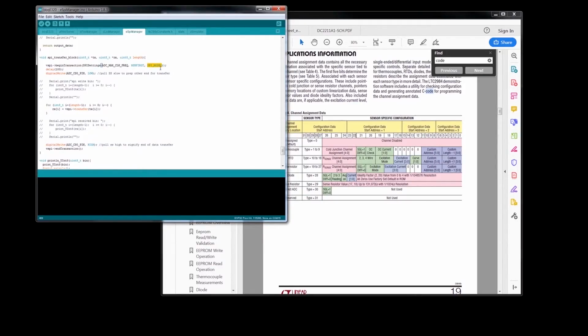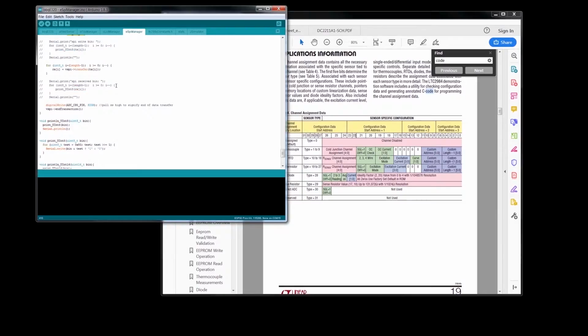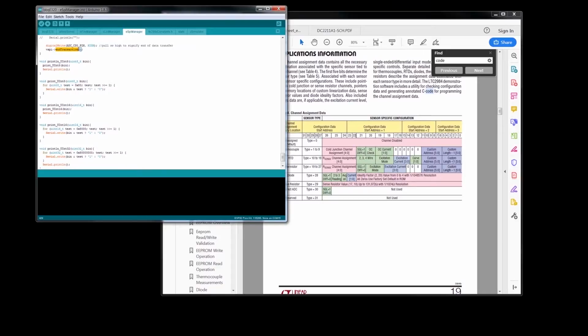We're giving it SPI mode 0, most significant bit first, and our max clock frequency, right? Then after we wait 100 milliseconds, we send the chip select low, telling the slave that we're getting ready to send it some data, and then we just send it the data, right? And then we set the chip select high, and we call this end transaction, all right?